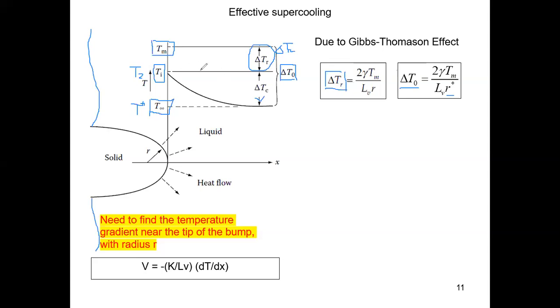Okay, and from the graph, if Ti is my melting temperature, which is the temperature of this tip right now, and far away from this tip we have T infinity, so this is the supercooling it feels. If we want to assign numbers, we call T infinity equal to -5, the melting temperature equal to 0, and my interface equal to -2. So I have a supercooling of 3.